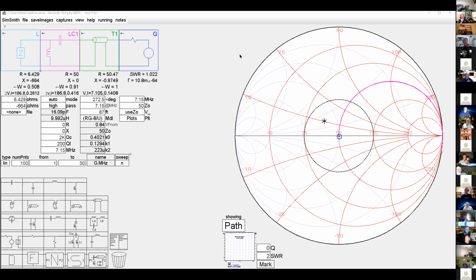Yeah, that's what I was looking for. Actually, I have a common mode choke right now coming out of the amplifier, and it helped somewhat, but it didn't really fix it. Yep. So I'm thinking if I get another one, put it up just below the balun, it may solve the problem. I think it'll help. When I'm running, some of the bands will tune fine on the HF auto tune. I've got a Palstar 1.8 kilowatt tuner. It works fine on some bands, but others it just can't tune.